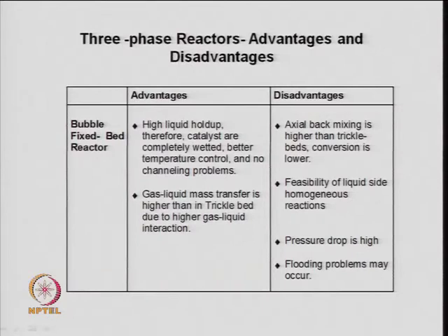Bubble fixed bed reactor, I thought that here also we should look at what a bubble fixed bed reactor is and what their advantages are. It is basically a fixed bed reactor, as we discussed earlier, and gas or liquid is being bubbled. So it has high liquid holdup compared to the earlier trickle bed reactor. It is a packed bed, and therefore catalysts are completely wetted, with better temperature control and no channeling problem.